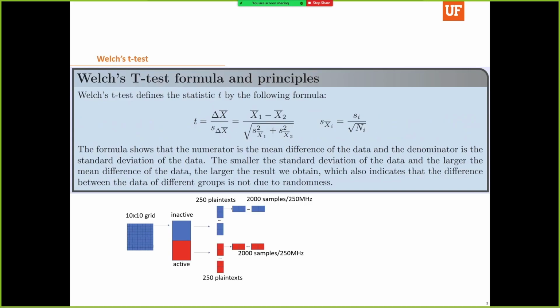Okay, the EM trace data we collected has 5 dimensions. In the dataset, the first dimensions refer to the 100 different points we took on the chip with horizontal and vertical space of about 2 millimeters. The third dimension refers to the EM trace data obtained with and without hardware Trojan activity. The fourth dimension refers to the 250 different 32-byte plaintext inputs, and the last dimension refers to the EM data in time domain.